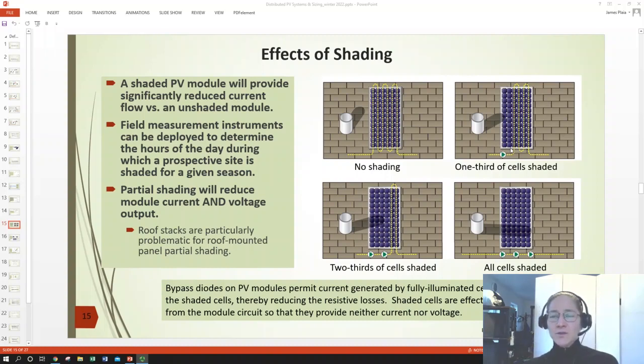So in order to reduce that resistive load from a non-producing cell, photovoltaic modules will come equipped with what's known as bypass diodes that can sense when we no longer have the correct voltage coming from a producing cell because it fell into shade, and goes, we'll just take you out of the circuit. So they're not giving you any power, these shaded cells, but at least they're not acting like big resistors. And generally on a 36 cell module, there'll be 3 bypass diodes. So each 2 long row loop can be taken out of the circuit as shade advances.